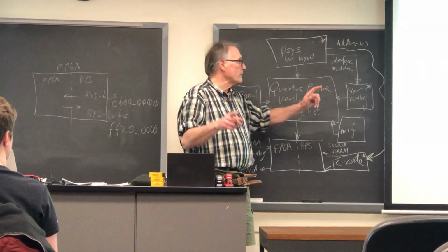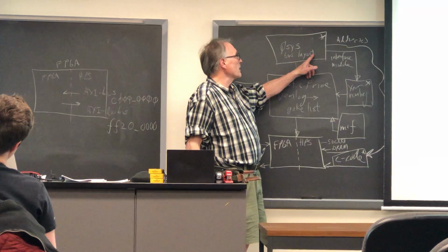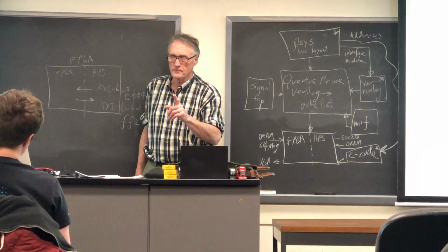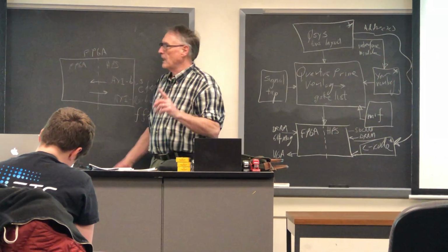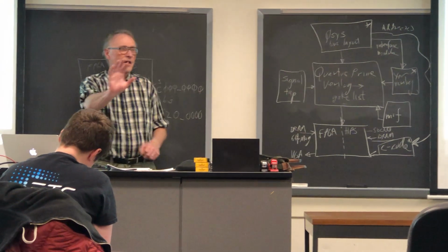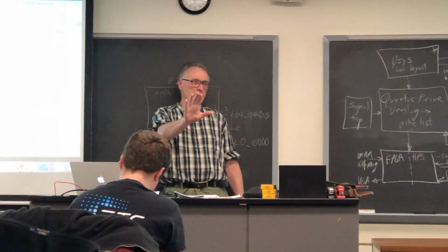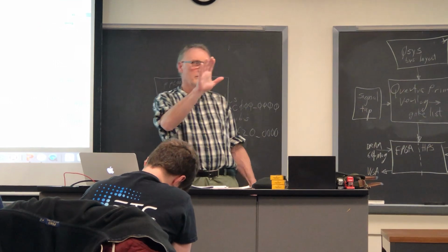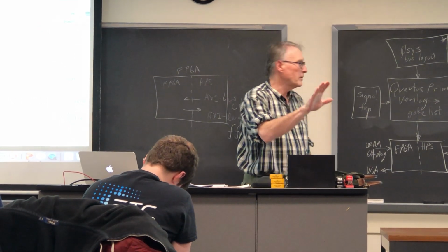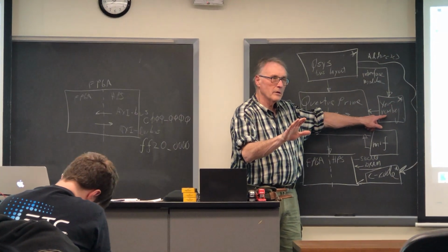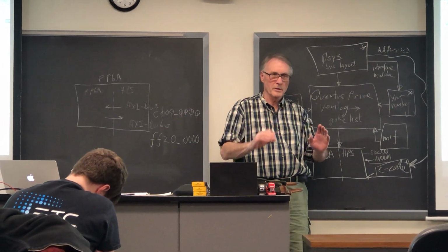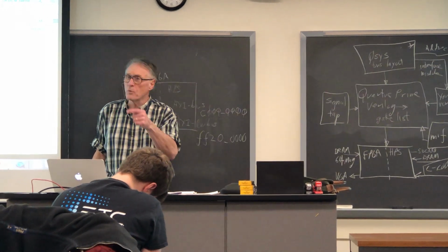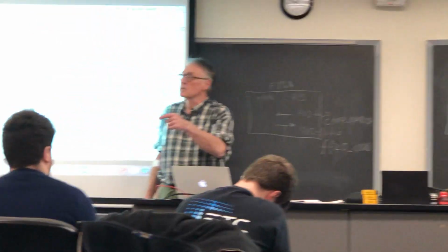Oh yes, you do. Okay, for testing you don't necessarily. Yes, you are going to have to modify Qsys because you're going to have to add parallel ports. At the end of this Qsys layout, you're going to have to add parallel ports so that you can communicate from the HPS to the Verilog that you're going to be using here. So one side of the parallel port is going to be on the Qsys bus, and the other is going to be exported to the FPGA so you can use the signals.